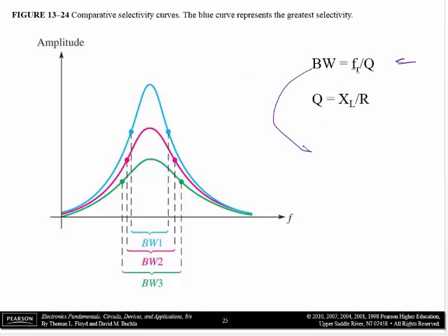So the quality factor Q right here, actually we can derive what the definition of the quality factor is. The Q equals the resonant frequency divided by the bandwidth. So something that has a very small bandwidth will have a very high Q factor. The Q factor will be very big, and that's a high quality filter. Steep and sharp and narrow, that's a high quality filter. It's actually how sharp the sides are that makes it the quality filter.